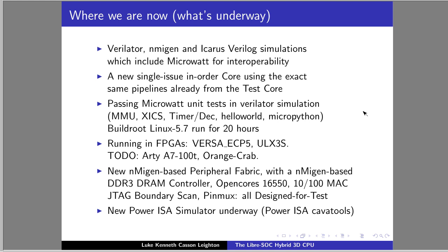So you dynamically construct the HDL there and then. You use Python-based classes and leverage the object-oriented nature of things. So rather than outputting Verilog using text file templates, you use the power of nMigen, which already exists, to output the HDL.